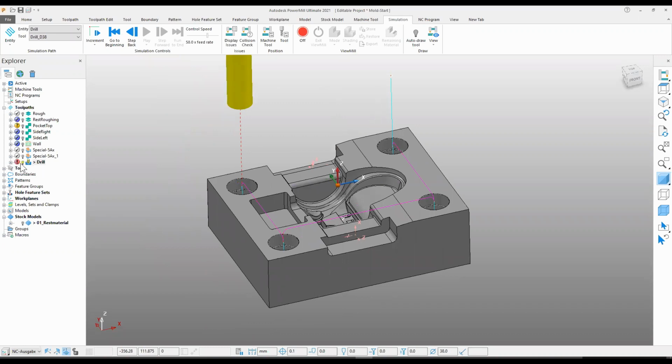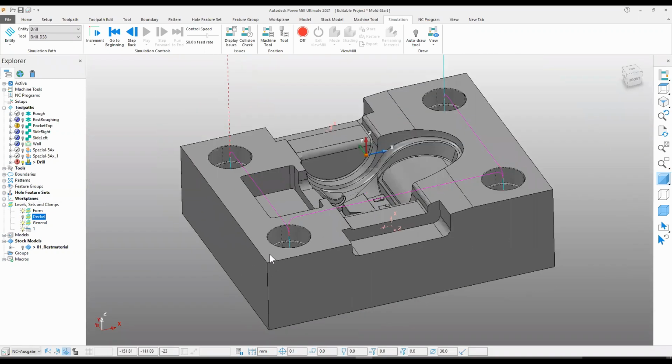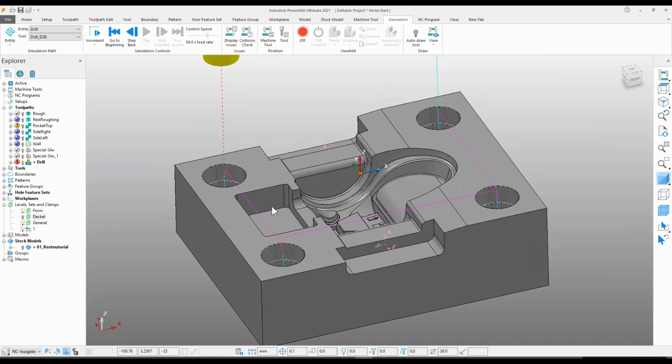If you're wondering, we got a red exclamation mark on this toolpath. The reason is that these holes are kept by surfaces that I don't mill inside while milling, but they are ignored while drilling, but I'm hitting them, so it gives me the hint that I drilled through some surfaces. But for drilling, this one is okay.